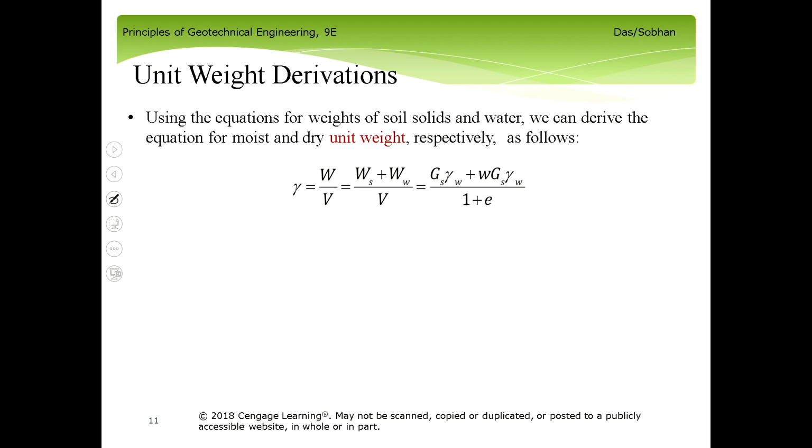So in here, first, let's see the relationship between gamma and the void ratio. Because we can test GS in the laboratory, GS can be easily obtained. And water content, you can use an oven to get the water content. Void ratio, of course, you can also get it. So the relationship between this and this, how to get from here to here, is in here.